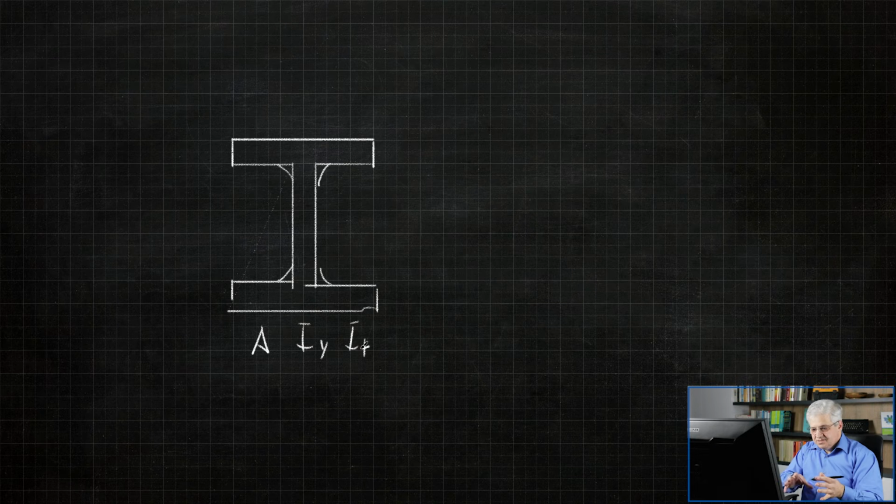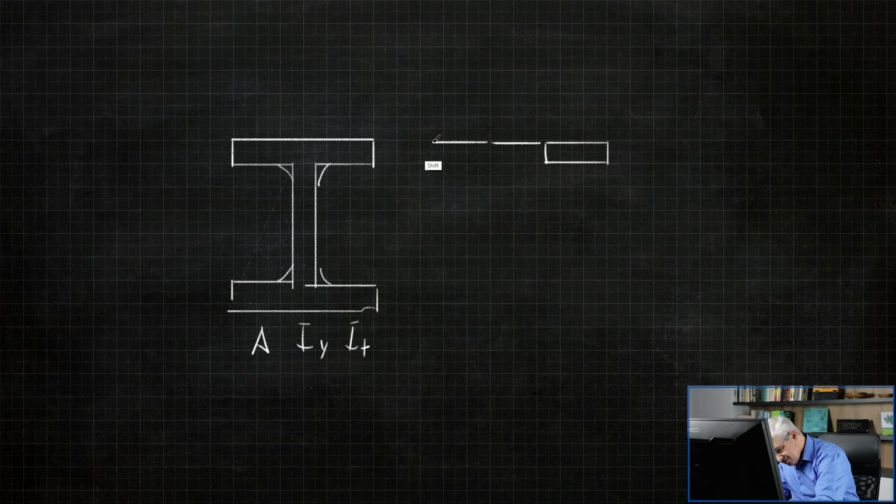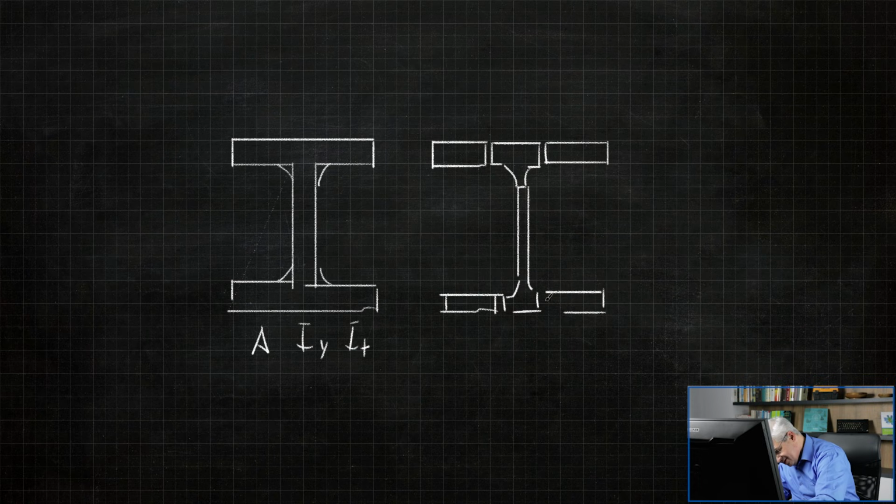But for the classification, this is not very useful, because Eurocode says that the cross-section has some parts. So we have to split the cross-section into some parts. Let's say this one, and the other side. Okay, I draw it completely, not so nice. So we split the cross-section into smaller parts. These parts are defined by width and thickness, and then we can look at each part at the ratio between the width and the thickness.